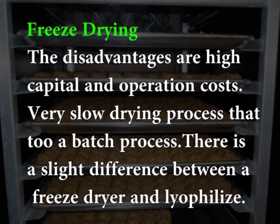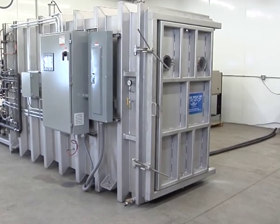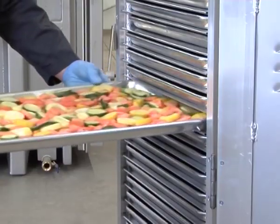There is a slight difference between freeze dryer and lyophilizer. In the former, after the freezing takes place, heat is given to facilitate the sublimation under vacuum. In the latter, no heat is provided to aid the removal of the moisture. In lyophilizer, very small quantities of samples only can be handled, whereas large quantities can be handled in freeze dryer, depending on the number of trays available and the dimensions of these trays.